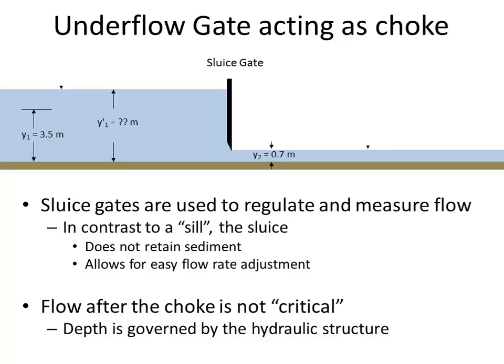Well, in this case, it's supercritical flow at, I'm sorry, downstream at 2. Under the gate, it's moving really, really fast. You can tell this velocity head is huge: 0.7 meters of depth and more than 8 meters of velocity head. So the water's moving supercritical under the gate, but it's subcritical at 1. So this is a case where this kind of obstruction has actually changed the flow regime from subcritical to supercritical. Does that make sense?